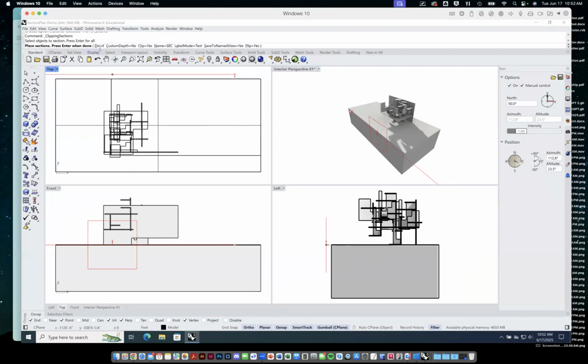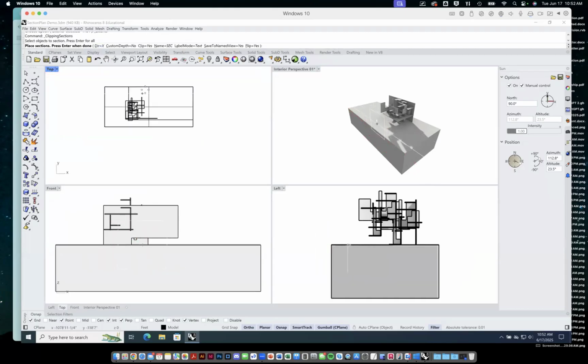Okay. And then it's going to say the direction is going to be X. Is that okay? And you can see the direction that it's going to slice the section. We're looking at a plane in top view from above, so we're looking at it as a line. And you can see the arrows showing what direction we'd be looking in. I'm going to say, let's turn this to direction Y. Oh, there we go. That looks good. Let's turn my object snaps off for a minute. Disable my object snaps. Those are annoying.